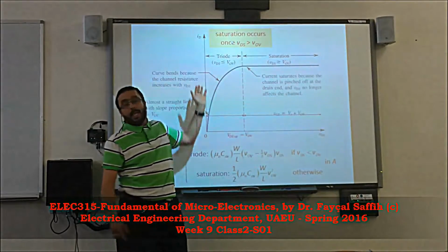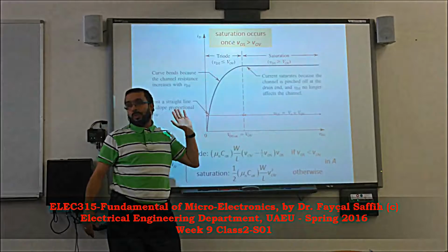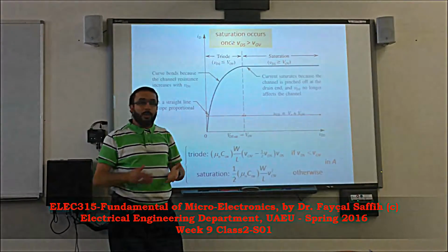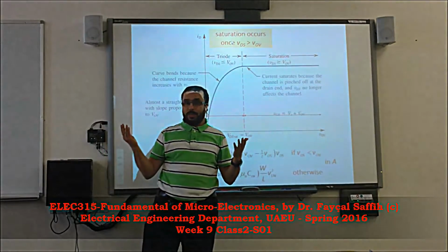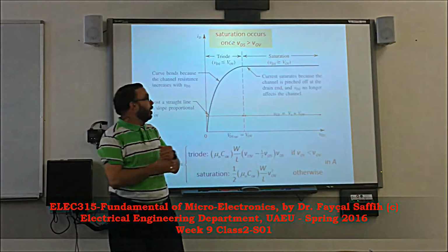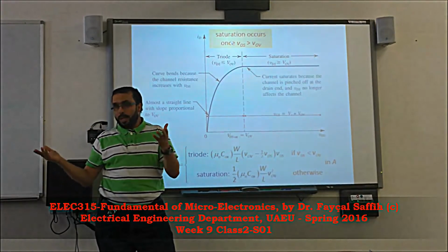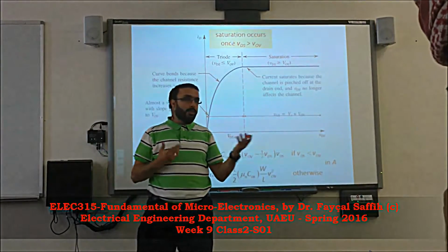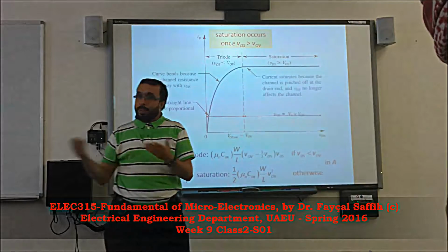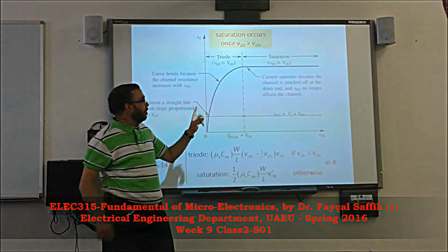So we said that the ID characteristic of a typical MOSFET, and this one especially NMOS, because so far we were discussing the N-channel MOSFET. Because still we have another channel. Why? Because the channel is built up of N charges, which are electrons. We have also a channel that's built out of P carriers, which are the holes. Okay, so remember this, very important.